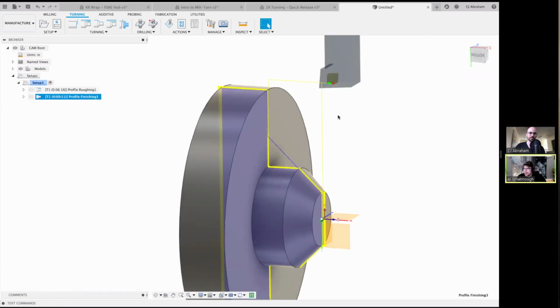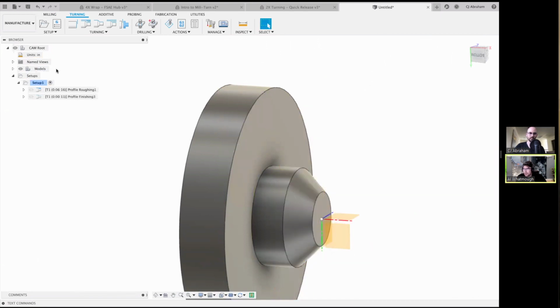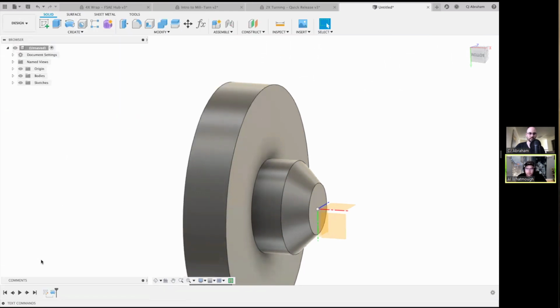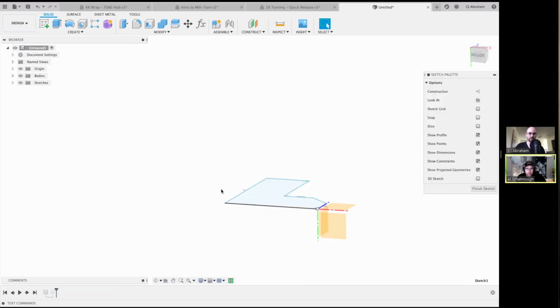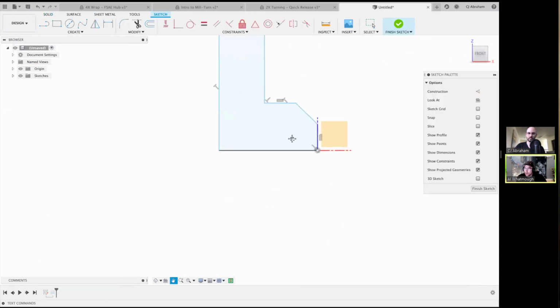And this would be a good thing to show CJ. Have it extend 1/2 inch maybe, so it makes it almost to that other face. And then later do a model change that brings that face forward. You wouldn't want to have to wonder if one of your toolpaths is gouging. You want to make sure your intent is preserved. Yeah, you wanted to machine past the edge, but you were never telling the software you wanted to gouge.